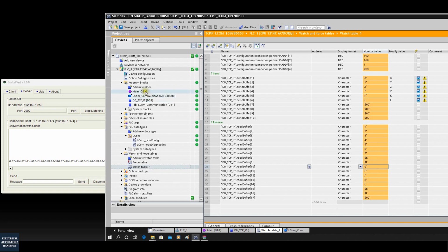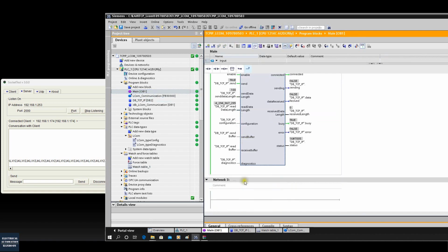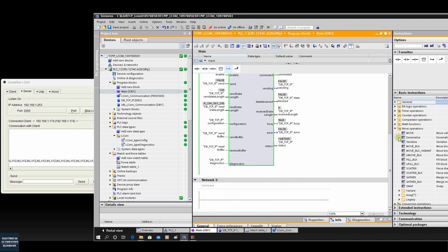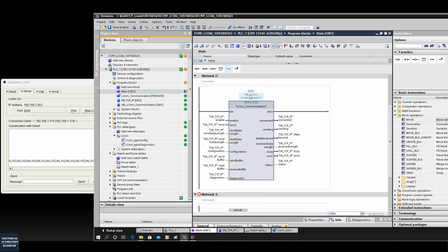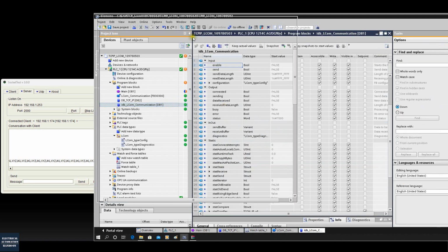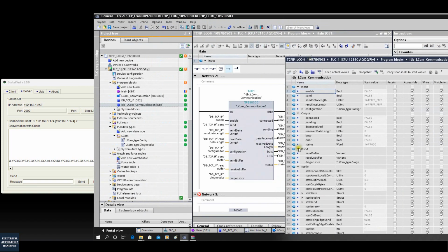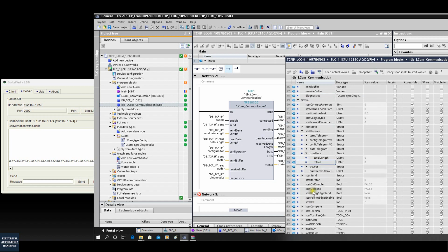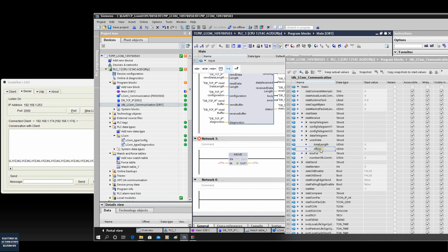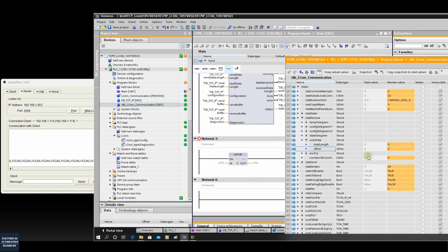So how do we force that? For example, we go to the main and drag in the move command. The target is that offset value. So we can go to this instance DB1, open this, float, and we can force that state receive, user data, and this offset. Okay, so we can force this offset. If we now monitor, we'll see my case is now 0.